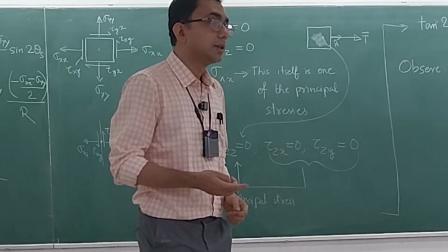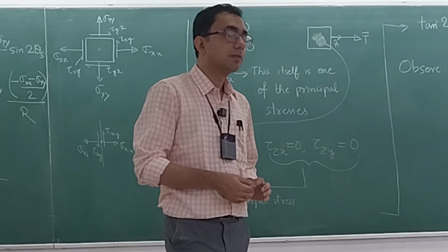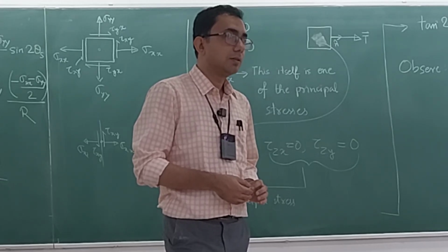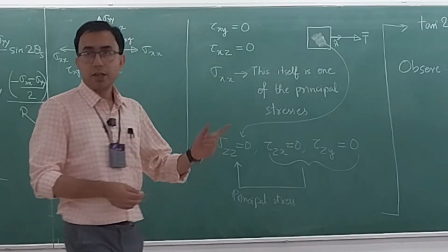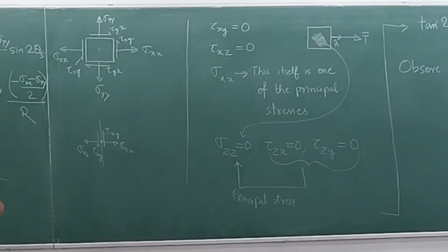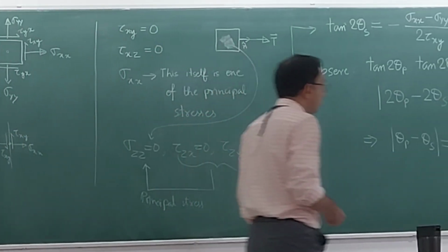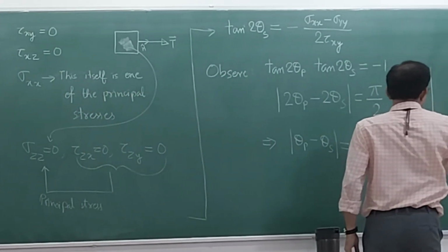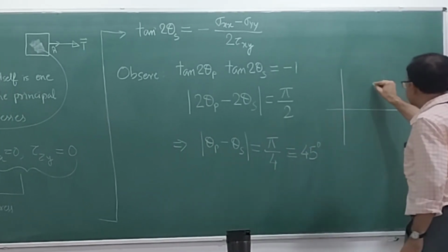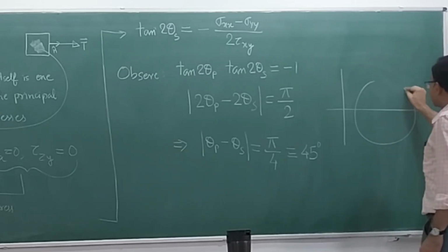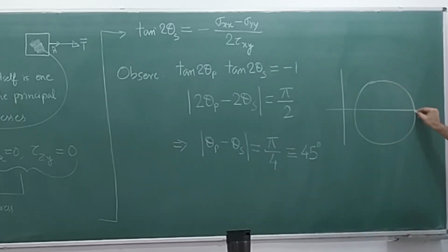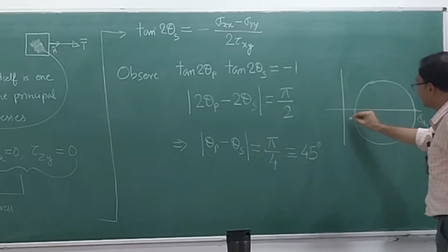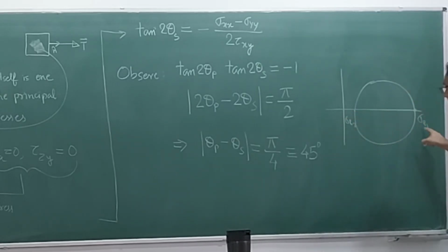You want to find out the upper point of the Mohr circle. So what Charit is asking is a very important question. Suppose we consider this Mohr circle, this two-dimensional version itself. We have understood that here we have one sigma p1, here we have another sigma p2. Sigma p1 is equal to sigma average plus r, and sigma p2 is equal to sigma average minus r.